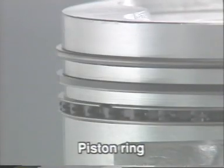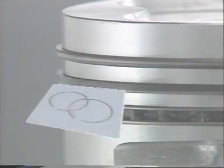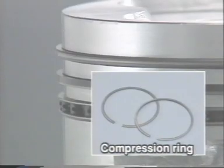The piston rings prevent compression pressure leakage through the clearance between the cylinder and the piston. Normally, each piston has 3 rings. The upper 2 are compression rings, which maintain the air tightness of the combustion chamber and transfer piston heat to the cylinder wall.